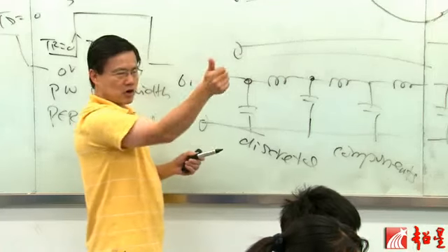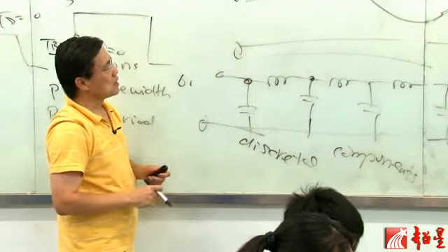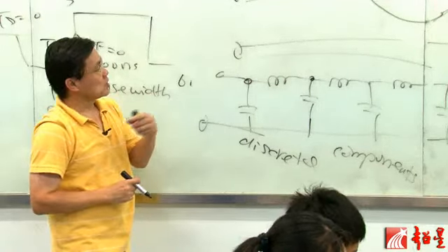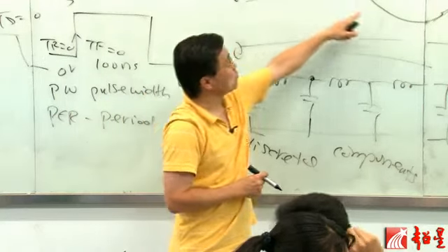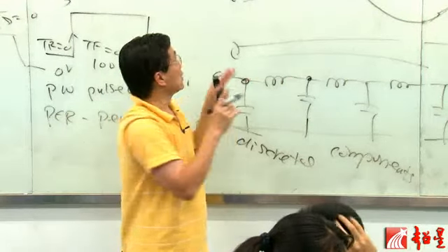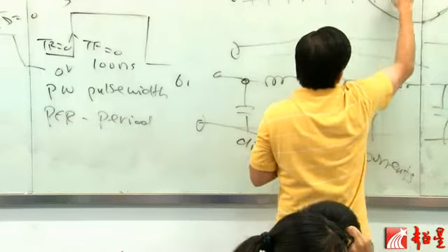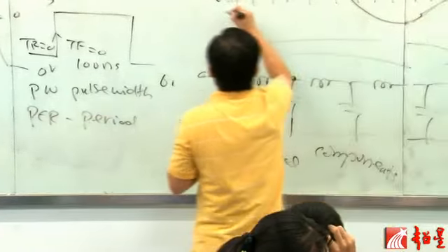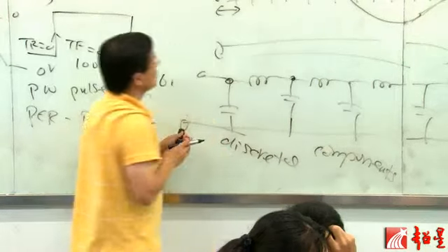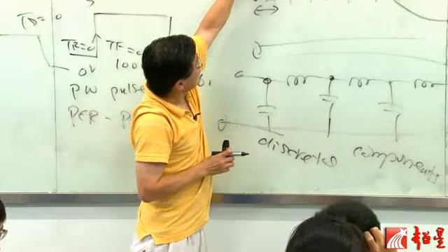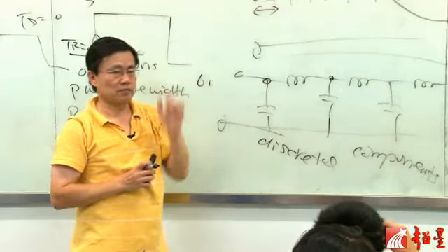So it's approximately 1/10, because if you divide this 1 wavelength into 10 pieces, then more or less you can assume that within each piece the voltage is the same.